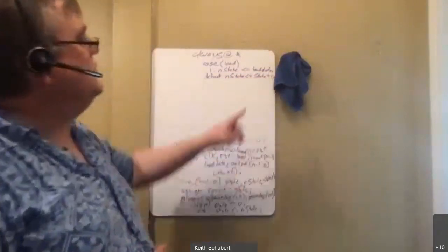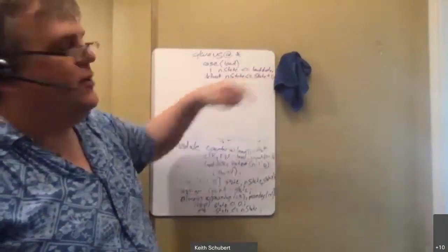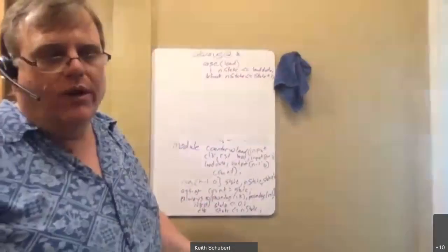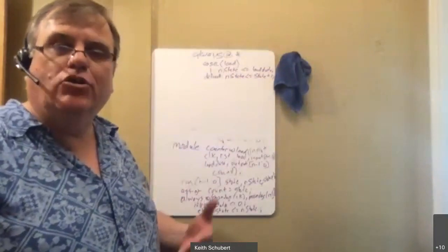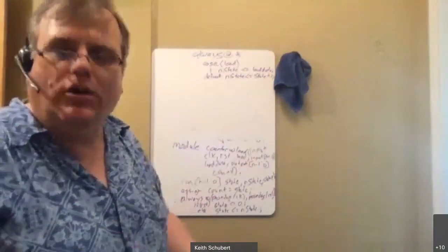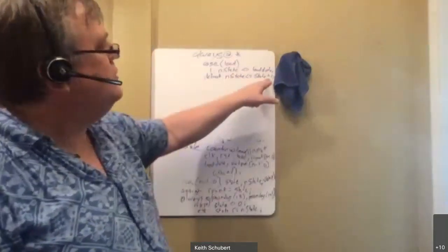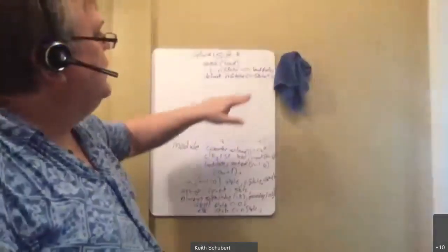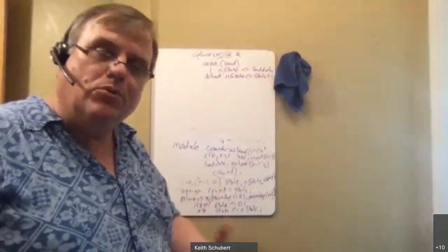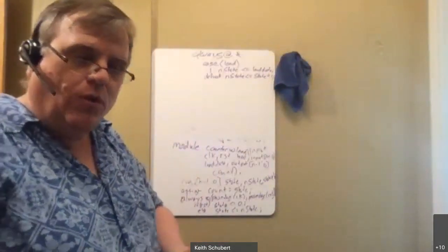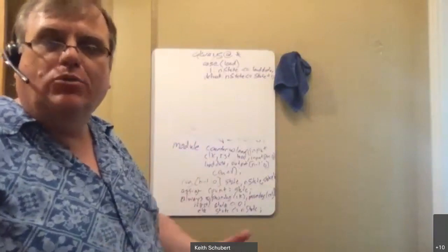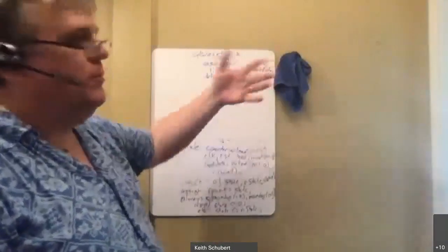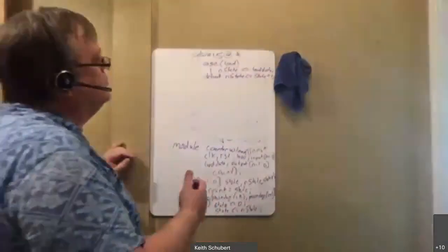So now it's got a couple options. It can technically do an adder if it wants and add 1 to it. It could also build, since we add 1 so many times, we actually built a special piece of hardware for this called an incrementer. And an incrementer just adds 1 to a number in binary. So it could also recognize this, go, oh, you're doing a plus 1, I can do an incrementer. The nice thing is that we actually have adders built into our system that are hardware adders, so they're very fast. So instead of building one, it'll often just take one of those hardware adders and run your numbers through it. So you get a very quick response off it.